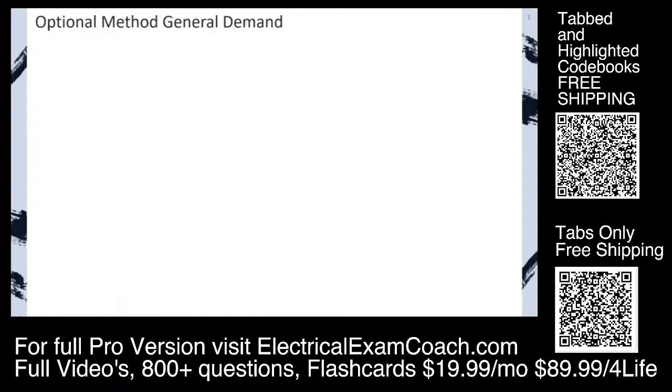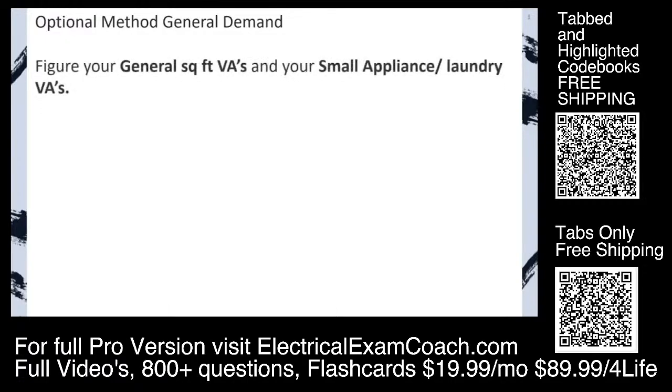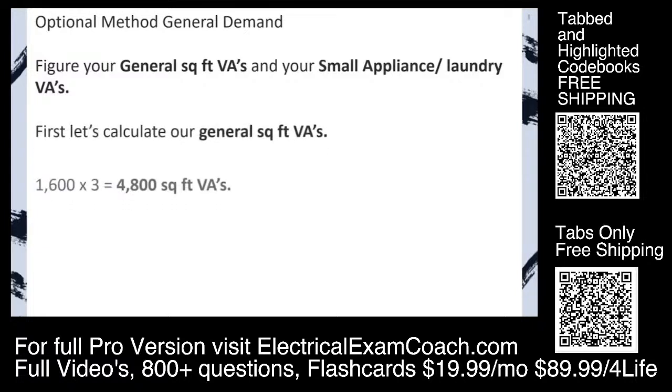Step 1 with any load calculation, whether standard or optional, is to get our general lighting demand. We're going to do our square foot VAs just like we did before. We take our square footage. Let's imagine we have a 1,600 square foot house. We multiply that by 3 VAs per square foot.